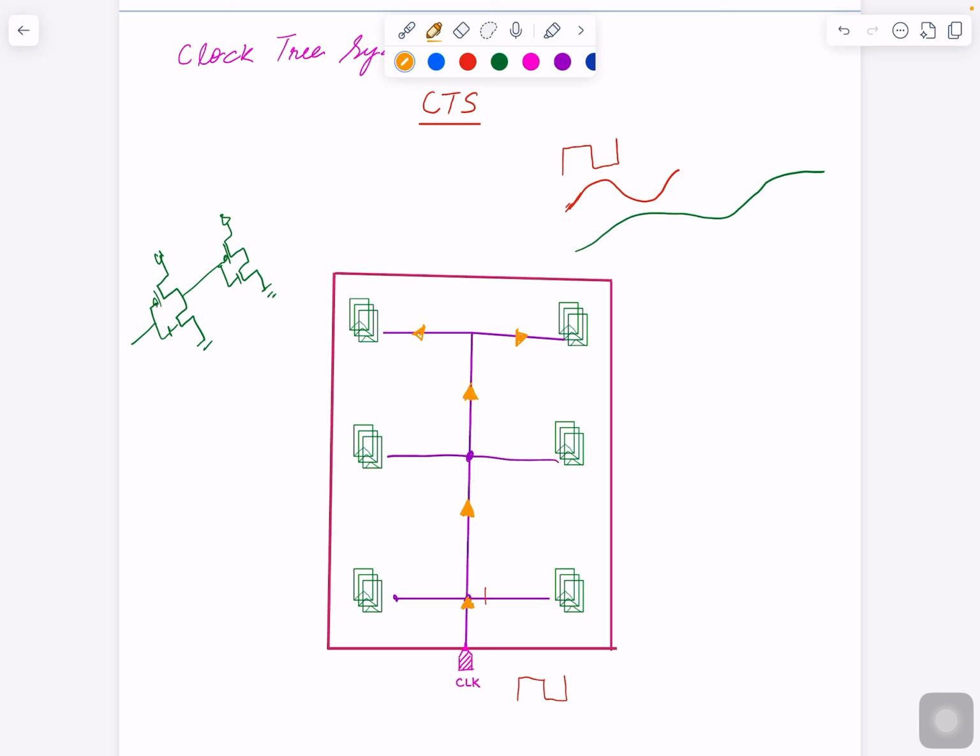You want to keep the distance pretty regular, so that they repeat after a certain distance together. So that's great for these two guys. Here, these two buffers can drive them. Here, this single buffer is enough, right? So in terms of recovering the shape of the signal, I think this will do the job, assuming these buffers are good enough to recover the shape of this clock. But they do create a problem.